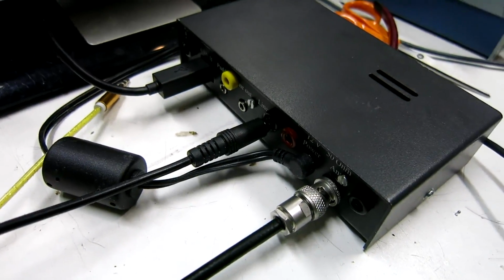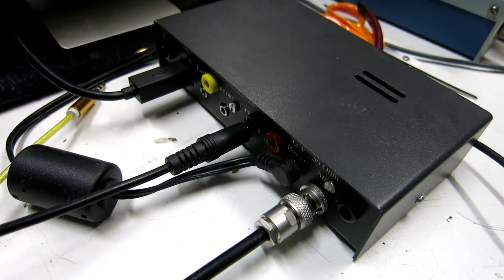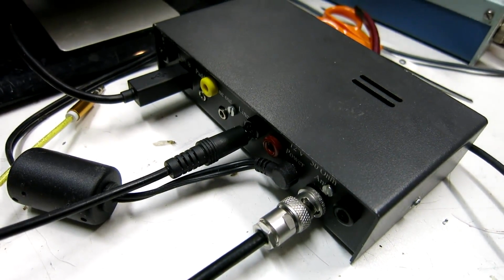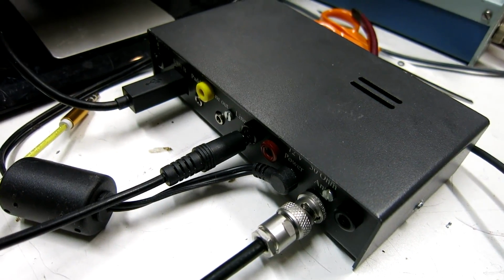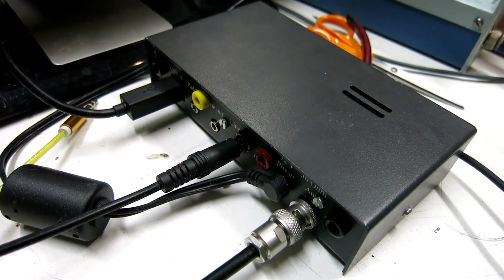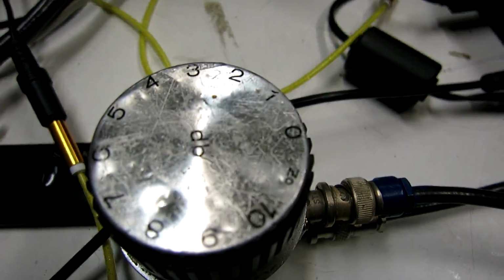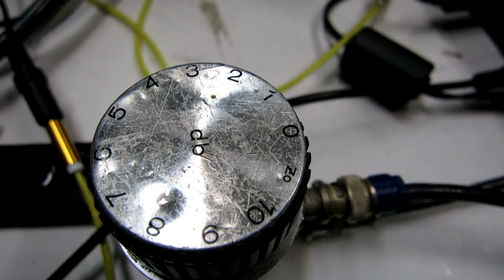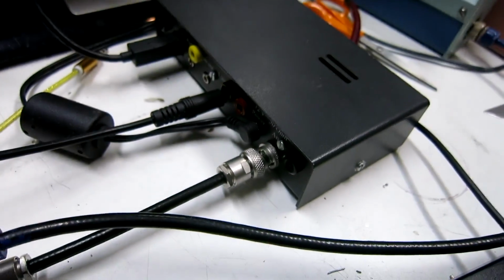This is a modified Softrock ensemble. The gain of the op-amps is reduced by about 10 dB and phase noise on the local oscillator is removed by use of a couple of capacitors. With this attenuator put in 0 as it is now, the signal level on the input connector is -8 dBm.